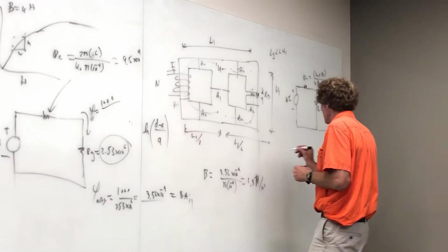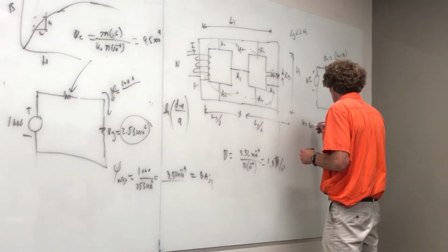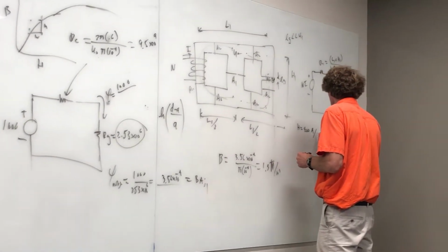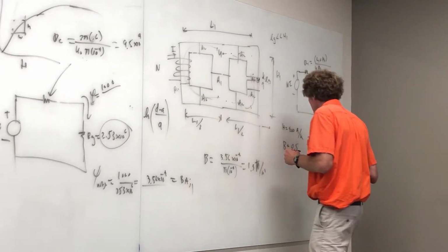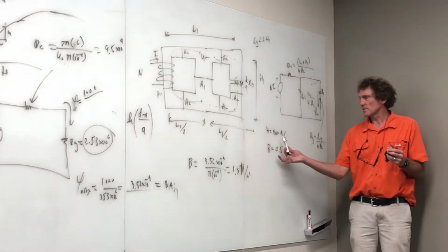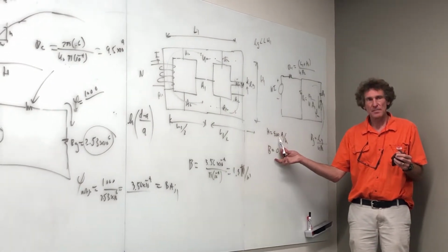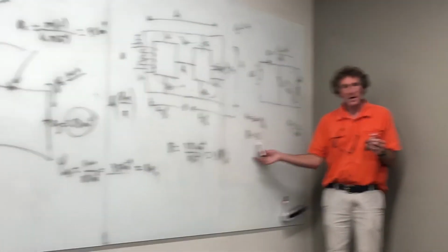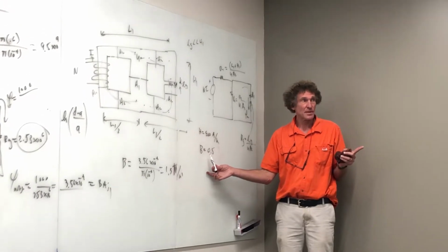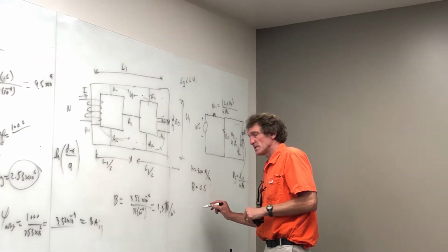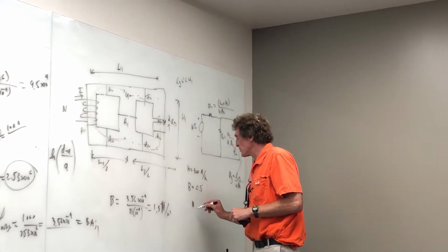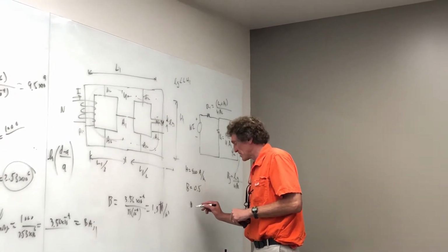So H is equal to 900 amp per meter, and the B field is 0.5. Can you see that? Take a look where the H field's 900, and then you get a B of that, right? Now here's the weird part. Watch this value of mu. What is mu? Well, mu times H is B, right?